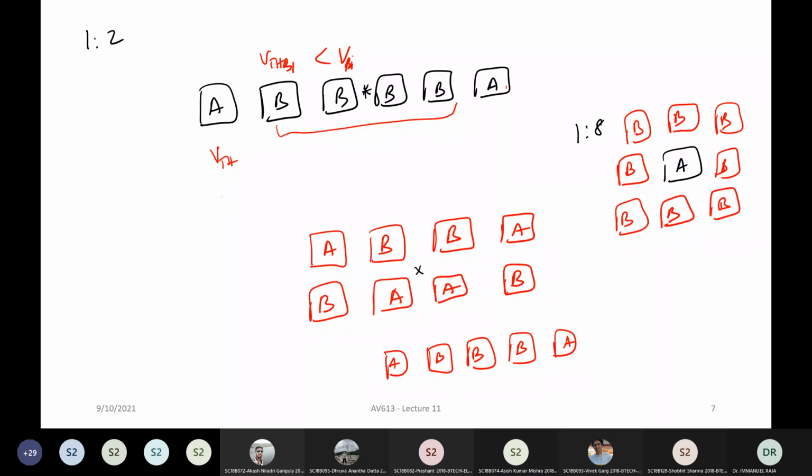Yeah, but I think what they have found is that it is predominantly linear. So a big chunk of the problem is solved by doing this common centroid. Yes, there will be some delta, which you cannot do anything about. But if you don't do this common centroid, it's going to be even worse, much worse. So that's the logic.